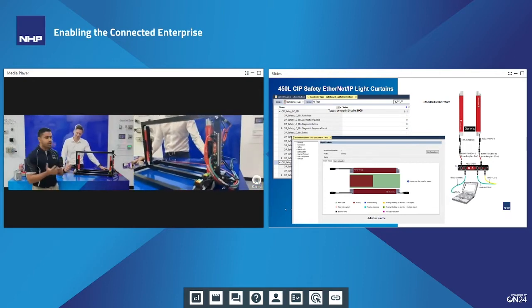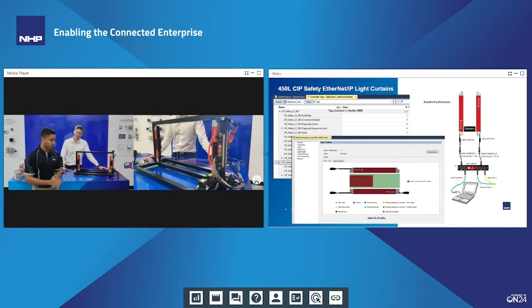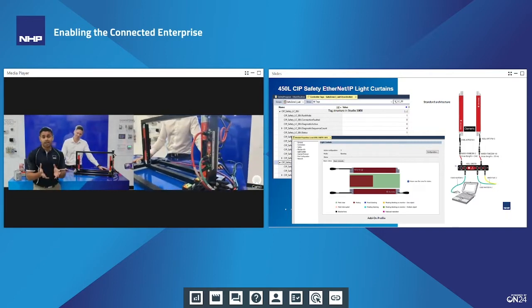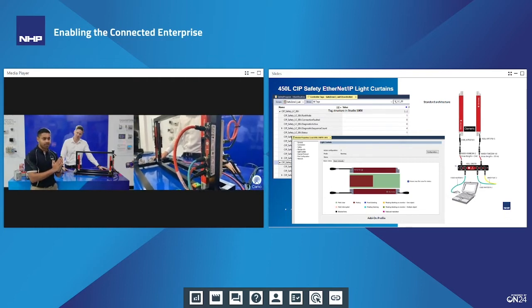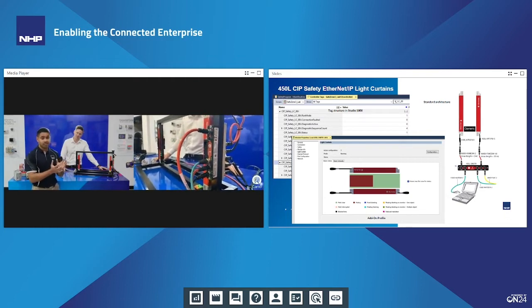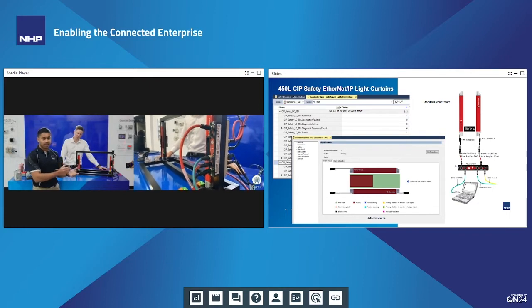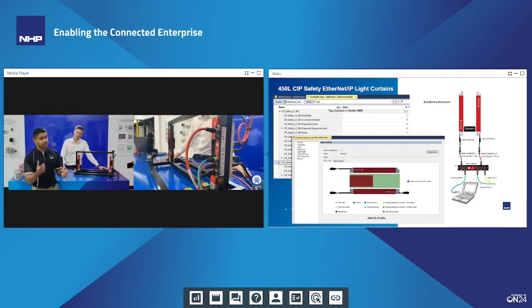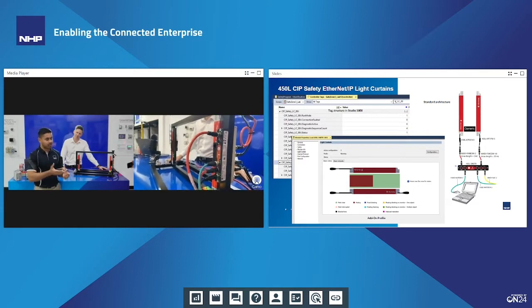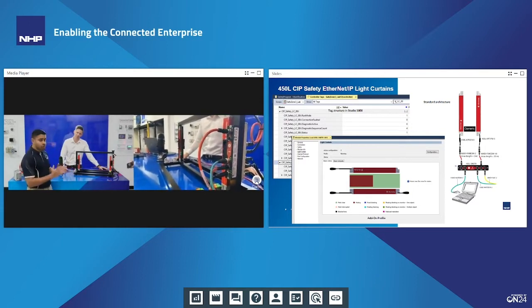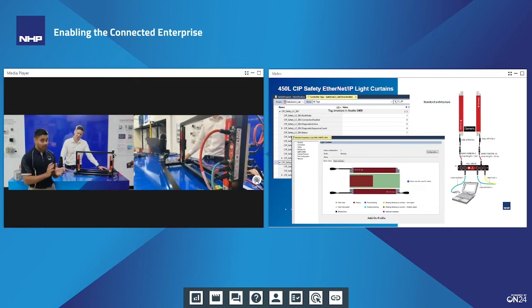And then 9 out of 10 times it's the alignment going wrong. What we've done in the past is use an alignment device that snaps onto your light curtain. This can be specific to a certain type of light curtain, and a specific person needs to have this, which means we need someone who knows how to use it to be on site. I'm going to show you how this works with our light curtains.